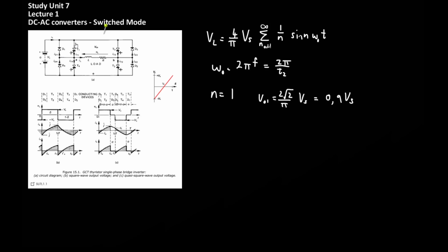An alternative to the bipolar mode is the quasi-square wave output mode. In this mode, an attempt is made to more closely simulate an AC signal in the output voltage by having an additional step in the output square wave. The idea is that by more closely simulating the desired output AC signal, it is possible to reduce the total harmonic distortion at the output, and thus have more power delivered in the fundamental. Another way of stating this is that the output RMS voltage can be varied by manipulating the shape of the square wave and introducing zeros into the square wave.